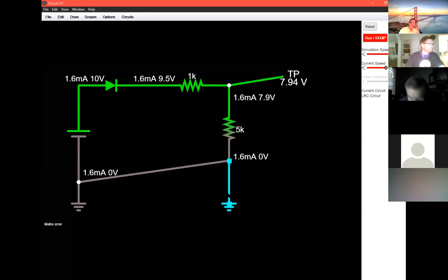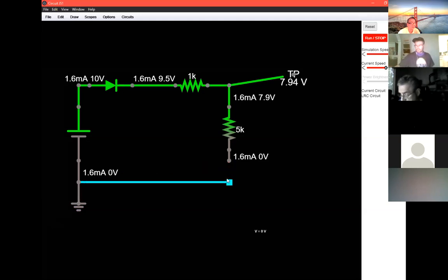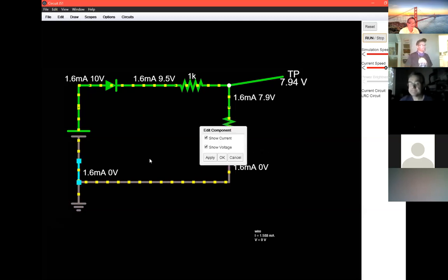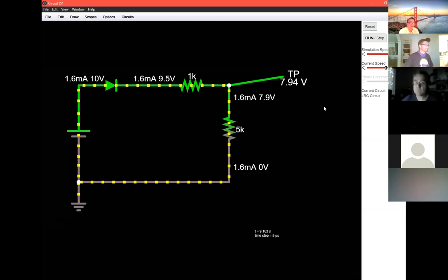Mr. Pham? Yeah. So you said 0.5. Is that for silicon? Because, I mean, is that for germanium? Because silicon is 0.7. Yeah, it depends on the diode. Okay, so Lowell, what diode is this? Is this a 0.7 or the 0.5? It provides a default, so the default is approximately 0.7.